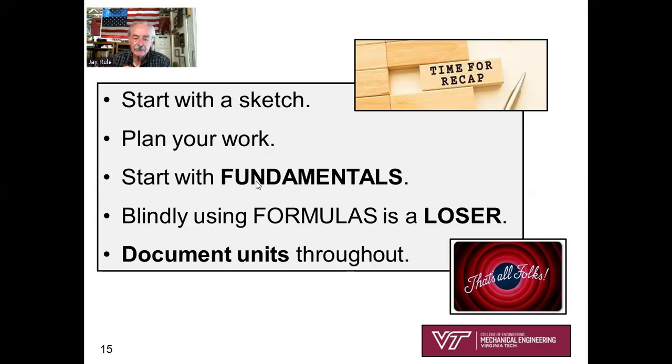What fundamentals apply to get me to the promised land? In this case, the first law helped us with that. That was a fundamental, the first law, and the definition of coefficient of performance, energy sought over the energy that costs. And then finally, the Carnot cycle heat pump coefficient of performance that was expressed in terms of temperatures. Those were the three fundamentals that we used to solve this whole problem.